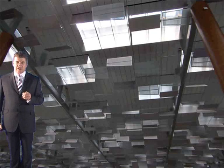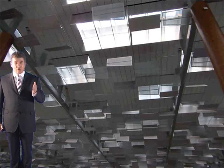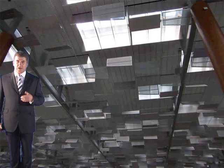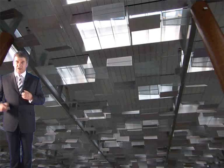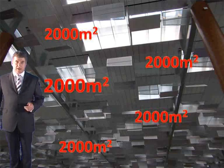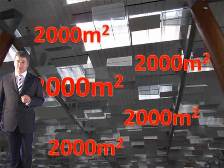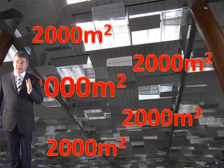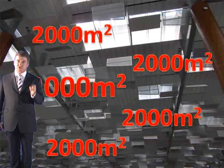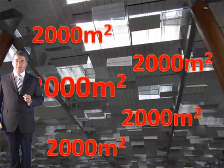Now the first thing to determine is the number of reservoirs that you're going to need in your building. So you need to work out how many reservoirs. For cost reasons, again, you're normally going to try and have the minimum requirement to meet the appropriate code. Now there are limits to the maximum size you can have for a reservoir. The maximum size for natural is 2,000 square metres. This can be increased to 3,000 square metres if it's for property protection only. Well in this case clearly it's not. It is a life safety one, so you've got to maintain it at 2,000 square metres.